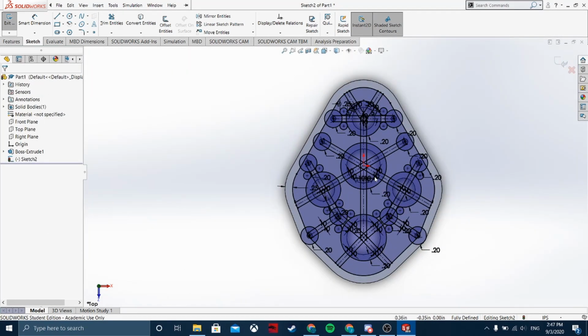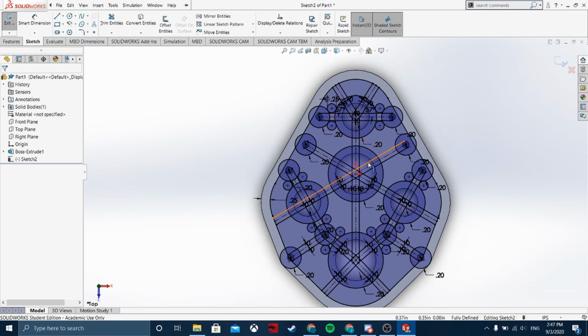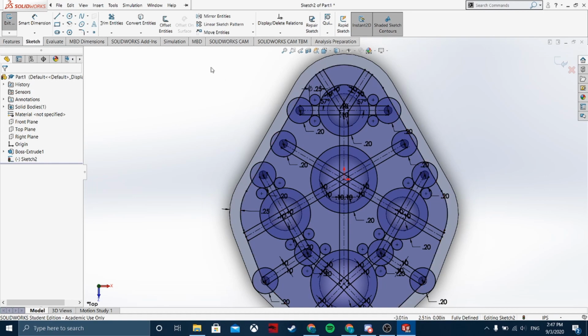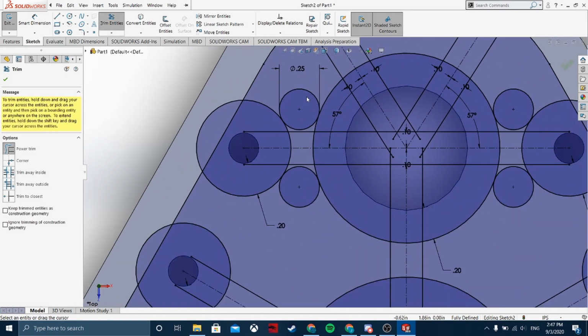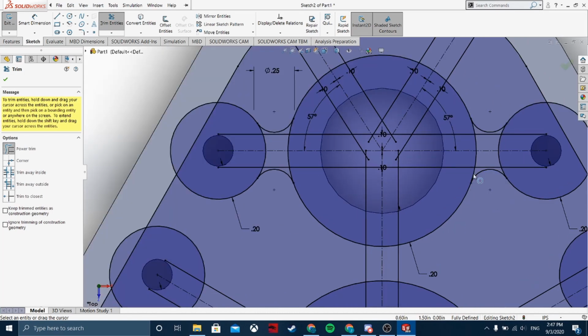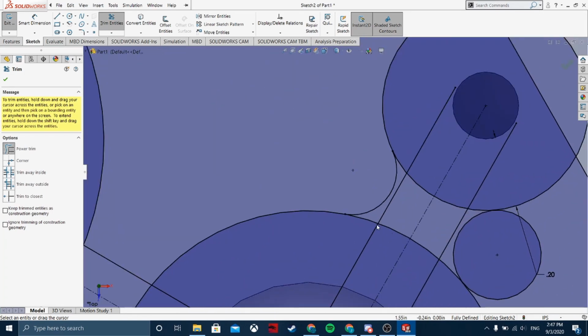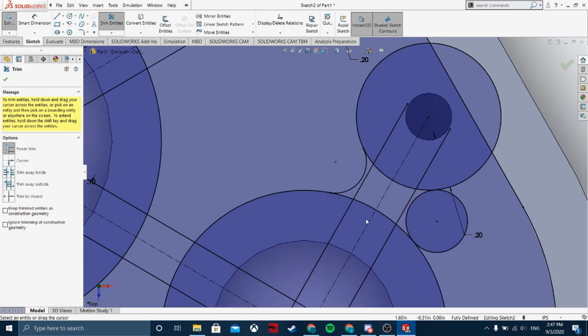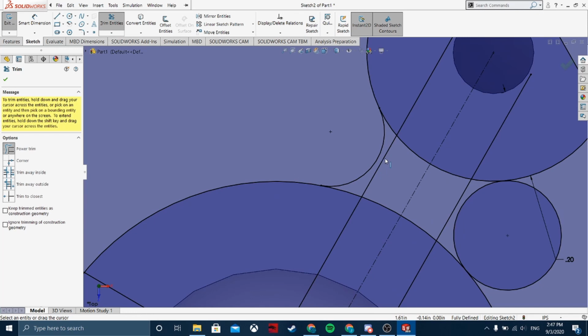Okay, so I made everything tangent, and here's where, I'd say, is the most tedious part. This time we're not filleting, we're trimming. It's not that hard. You just need to trim it like this, just the parts where you don't need. Notice how there's this curve? If we filleted this, there would be one curve here, but then it would stop here and create this sharp edge, and then create another.